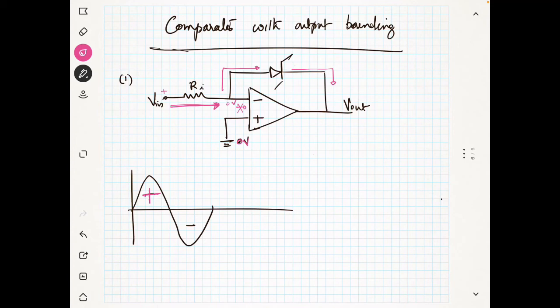Now if it is flowing like this, the Zener diode here is plus and this is minus, and this is 0.7. I told you this voltage will be the same as this voltage when the feedback loop is connected. Whenever the feedback loop is connected and there is a current flow through the feedback loop, then due to the virtual short, due to the virtual ground, which I have explained before, this will be 0 volt. So what is my output?